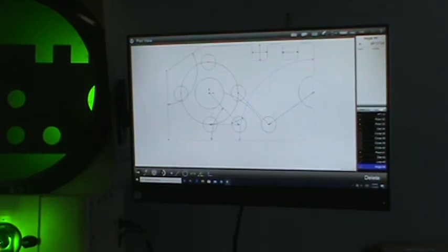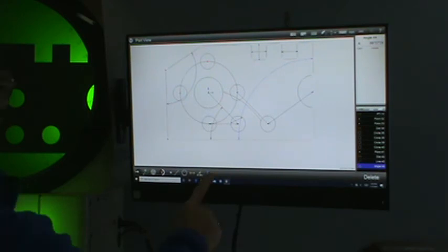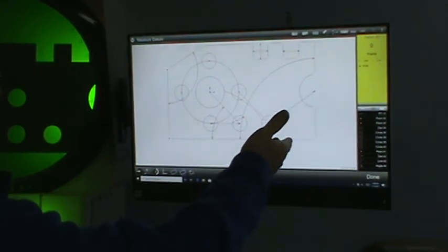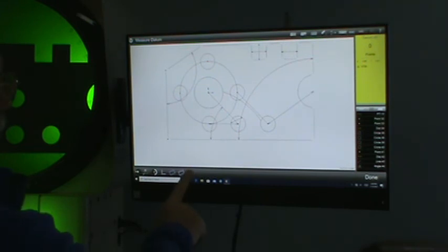And also your alignments, whenever you want to align a datum feature, because that's one of the key elements too. When you're measuring something, you need to really do an alignment on it to make it square to the world. So whenever you do alignment, I can come here and measure a line until I want to create a datum there, or I can just tell it that I want to create an alignment and measure my lines.